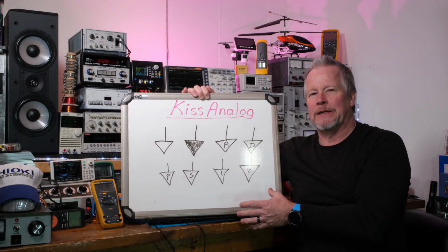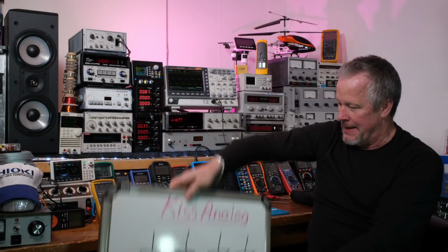Basically I just want to talk about ground symbols and what they are, and talk a little bit more about these kinds of grounds and the difference between the chassis ground or the power, safety grounds. What we just talked about were the types of grounds that are mostly meant for safety, and then for signals, to show the difference between the power grounds that are really meant to keep us safe and the kind of grounds we use in our circuits, our circuit grounds, our signal grounds.